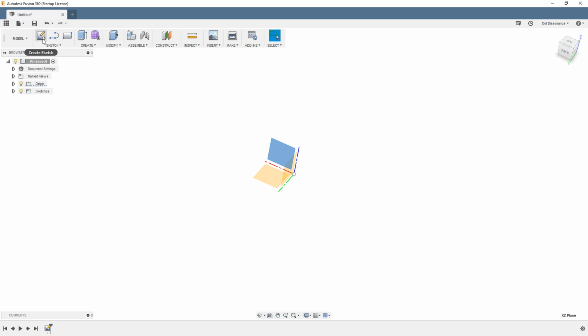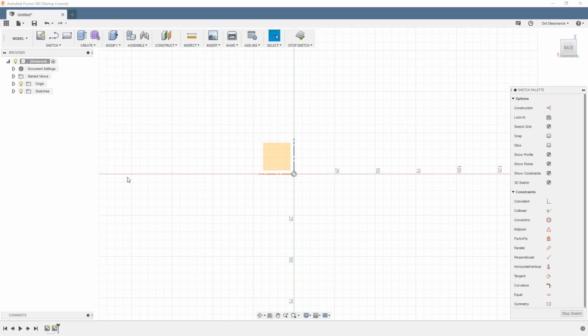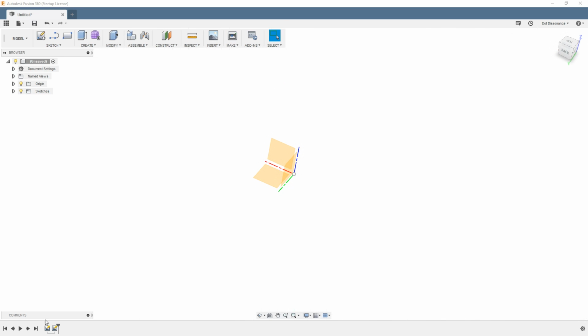So I want you to click on sketch, and then I want you to go to the XY plane to start making your part. And you go, okay, I'll click. And then I say, okay, go ahead and click on the XY plane. And you go, oh, okay, well, I guess I didn't have to. Anyways, and I'll continue on making my part. And you should realize you're on the wrong plane now. So as you go down the road, somewhere down, multiple steps, all of a sudden you realize, oops, I did something wrong. And this can be fairly catastrophic, especially when you're new. And it might cause you to have to redo or undo everything or start all over again. So be very mindful of that.